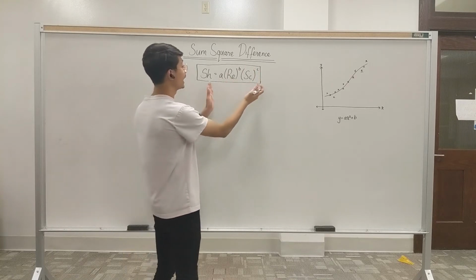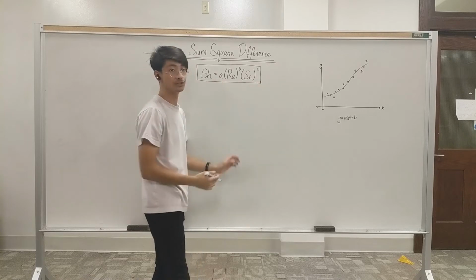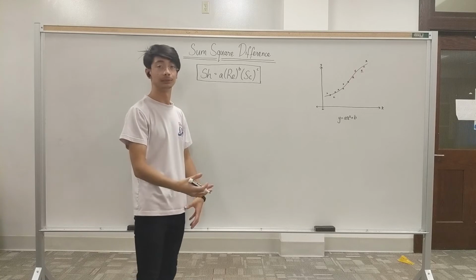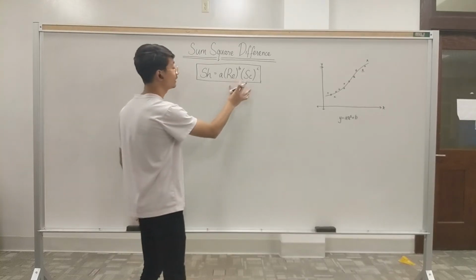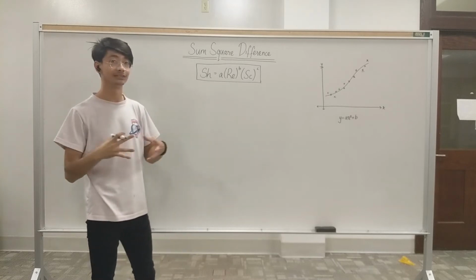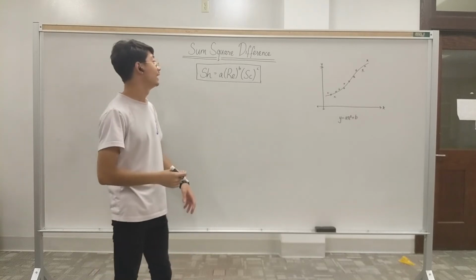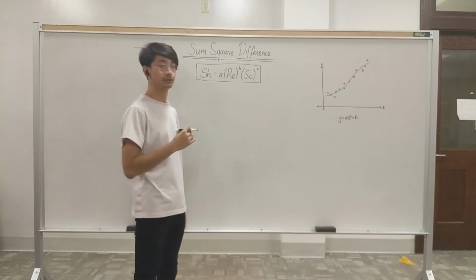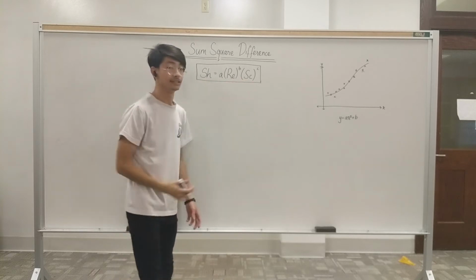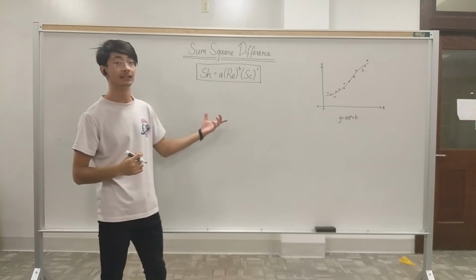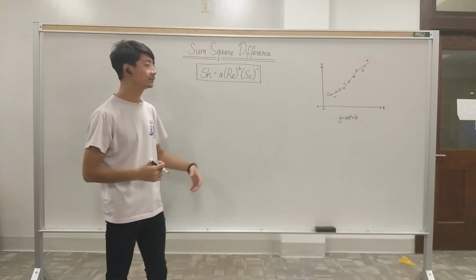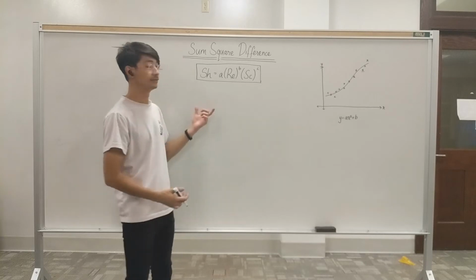then we're going to try to calculate the right-hand side of the equation, since we already know what the Reynolds number and Schmidt's number are going to be from our experimentation. And we're going to subtract that from the Sherwood number that we also got from the experiment, and we're going to see what the difference between those are. And we're going to make multiple guesses for it, and then we're going to see which combination of A, B, and C gives us the minimum possible value of the difference between the left-hand side and right-hand side of the equation. So let's go a little bit more in depth about this method.